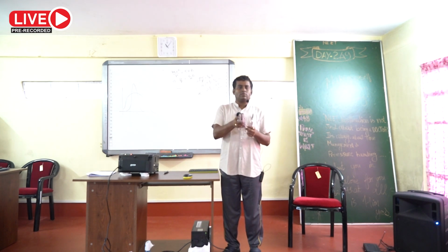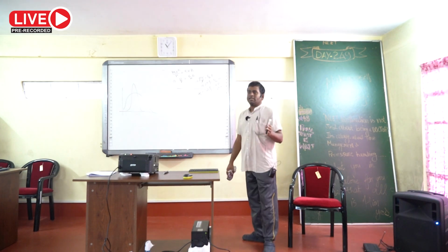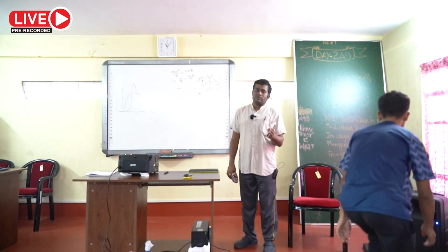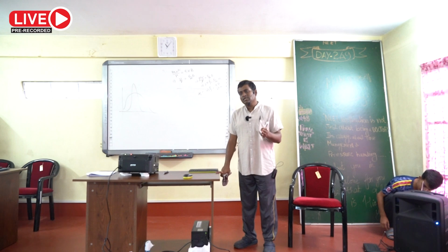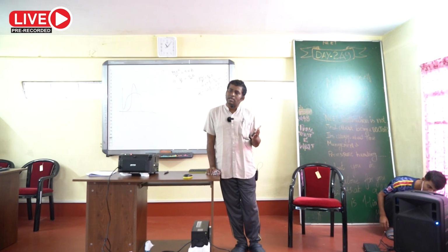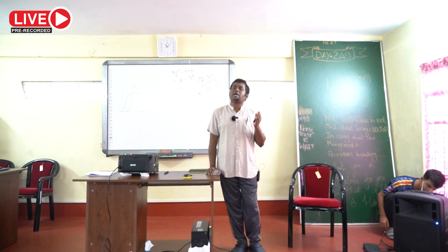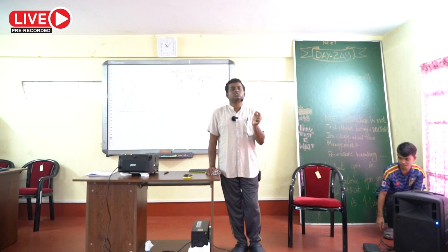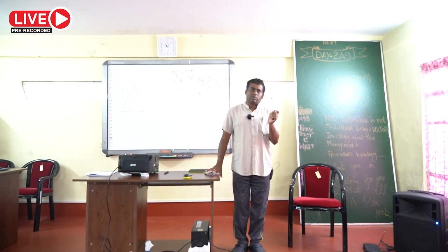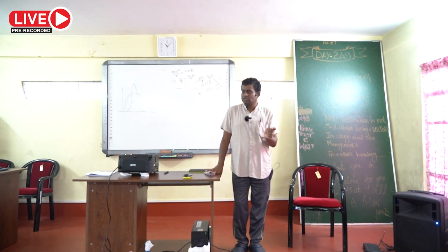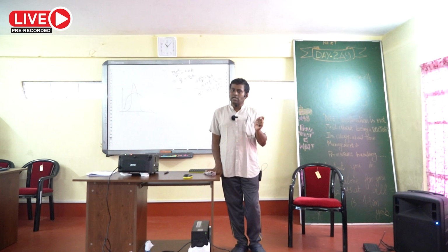So you have to check from the following combinations which one will give you a better resonance curve. You can measure either the quality factor, then you have to calculate which combination gives the largest value of the quality factor, or if you measure in terms of bandwidth, which combination gives the lowest bandwidth. So you have to read these two portions, sharpness of resonance, and under it two measurements, quality factor and bandwidth, to solve this entire question. Clear?